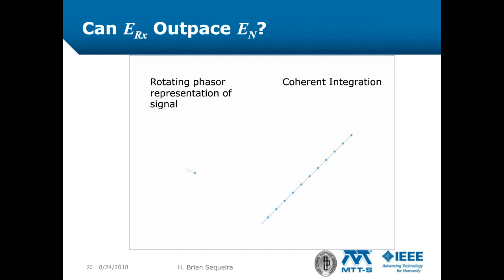Another way of sampling signals is non-coherently, in which the SNR grows as a square root of the number of samples accumulated. This is a less efficient way of accumulating energy, but is unavoidable in certain circumstances. An important point to note is that the foregoing considerations establish lower bounds on the detection time, irrespective of application. That is, detection time should be long enough to accumulate a statistically significant number of samples and to integrate sufficient signal energy to obtain SNR to meet the specified probability of detection and probability of false alarm.